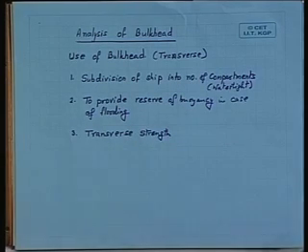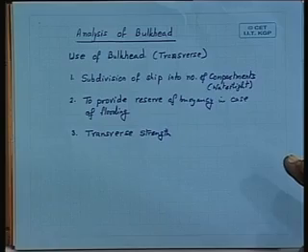So, the water pressure which is being acted upon on the sides is getting transmitted through this, and the bulkhead comes from the two sides in sustaining the in plane forces. So, that is the type of load which is being transferred to this transverse bulkhead.